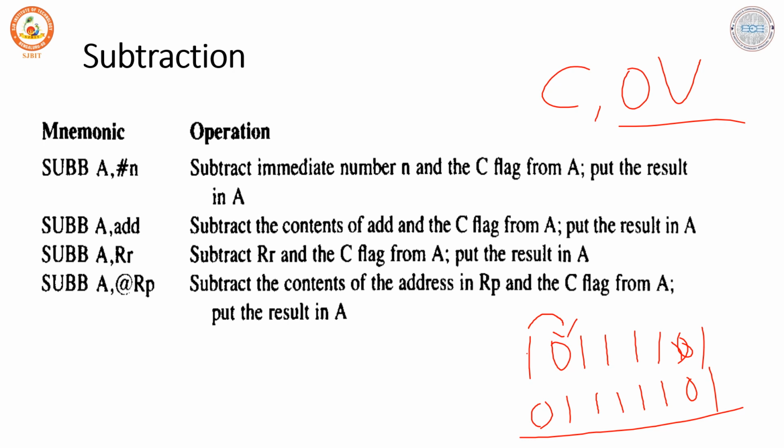During these arithmetic operations, it is good practice to clear the carry before performing any operation. Most arithmetic instructions affect the carry flag, and some instructions use the carry flag information. So it is very important to clear the carry before we perform the subtraction or any arithmetic operations. Here we are showing some examples using different addressing modes.